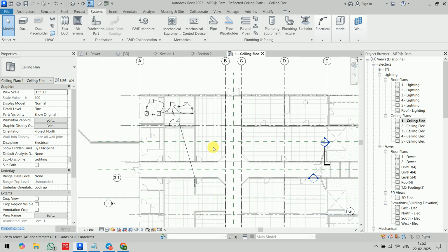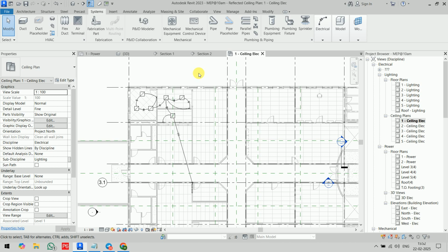In electrical, there is an information and communication system. Let's say you have to place all the smoke detectors, flame detectors, and fire alarm systems. So you first need to place all the sensors on the ceilings. If you go to any mall or theater, in washroom areas and lobby areas, you will find smoke detectors and flame detectors.